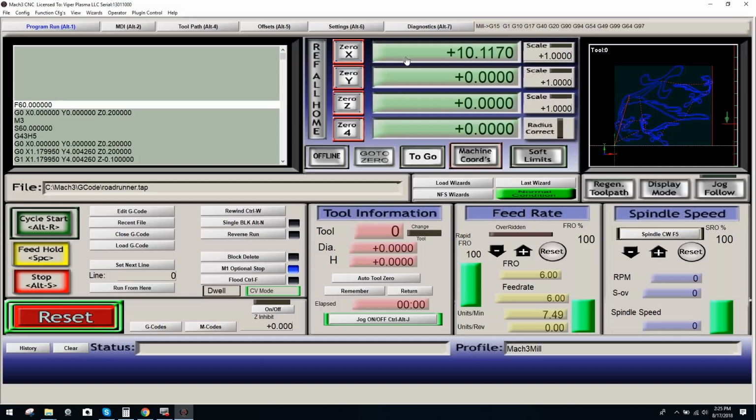Okay. And now we know our table, and this is only for your reference to put this actual measurement into the soft limit settings. That is what we're doing with this. That is why we're jogging all the way to the table extreme after finding our 0 point on the table, once again, in a negative actual motion for setting that. And the reason we do that, again, is so we have the 0 start position, and then we're measuring our maximum limit of the table.